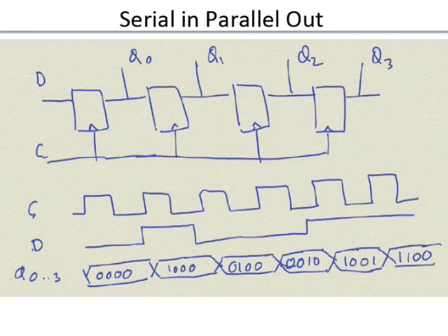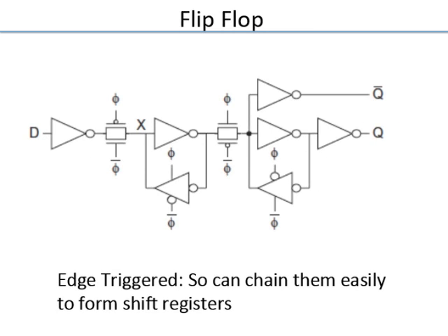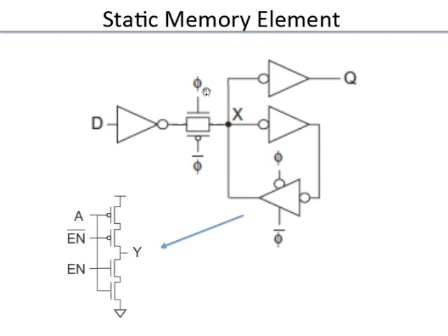Setup time will be determined by charge. And hold time will be... they are related basically. Hold time problem comes when things happen too fast. For example, you might have a slow charging but fast discharging perhaps, and that could lead to a problem with the hold time. Essentially, it has got to do with how quickly you change the state of that node X.